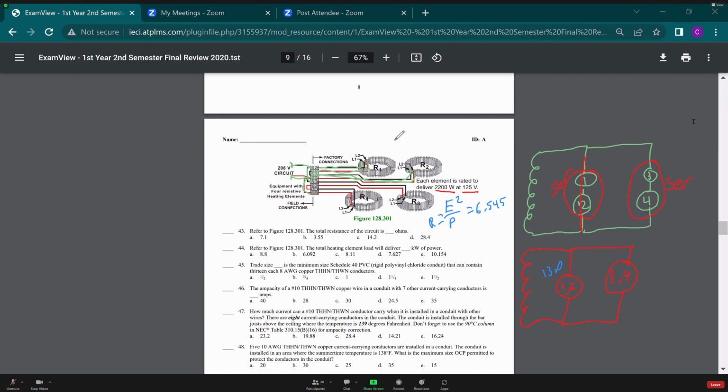Yeah, that is. Let me erase these. Oh, I probably did exactly the same thing as you did because I got the same resistance. Yeah, taking a look, making sure that we're putting in 125 volts. That nameplate rated said 7.10. We'll just stick with 7.1. That gets us our combined resistances of 14.2 for each of these sets.